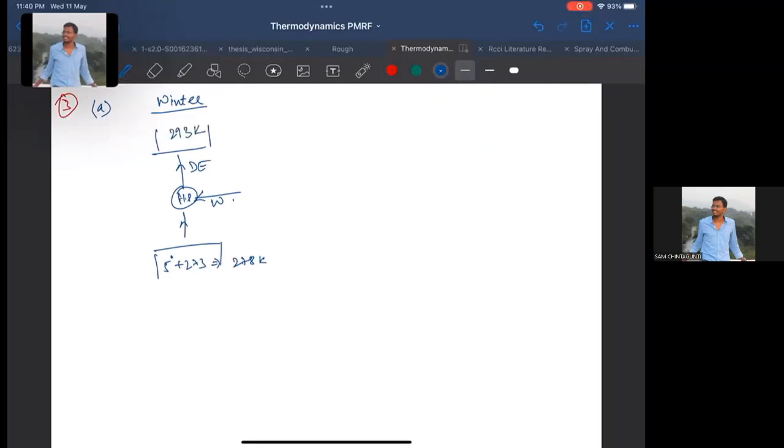And then they are saying that heat transfer through the walls and roof is estimated. So there is a heat transfer which is equal to 0.525 kilojoule per delta C difference, right? So that is equal to 0.525 into the difference here, which is 20 minus 5, so 15 kilojoules, inside and outside. What is the minimum power required? I think this is actually kilojoule per second, right? So it is actually kilowatt.